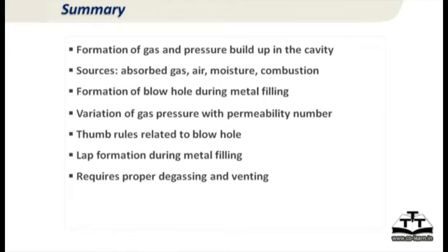And there is no discussion about the need for proper degassing and proper venting. These are essentials. Degassing is one thing that cannot be emphasized enough, especially in aluminum alloys, because almost everything else in foundry you can control by design, but gas porosity you cannot control by design. You have to control it only by process conditions, only by degassing properly and following all the rules of the game.